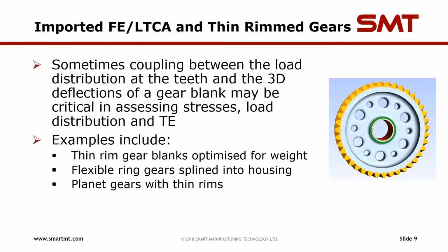The first step of this is to introduce the new spline functionality for getting more realistic deflections of that gear. But moving on from there, we also want to improve the coupling between the LTCA and our imported FE calculations as well. And hopefully you should see the results of this coming in the next year as well. So this will be actually using the detailed gear blank shape within the tooth contact analysis.